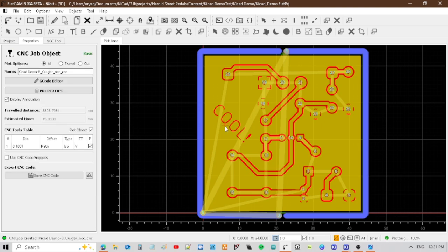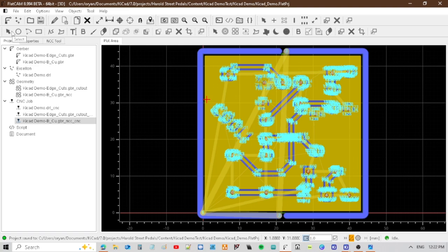Okay, so we did that pretty quickly. Is it going to give it to us? This is where sometimes it'll plot and finish, but the G-code will be empty. You won't get it all blue like it just went. It'll stay red. The numbers won't appear. Save. And that was what that fix was when I made the geometry. I made it a little bit bigger than the bit, and it seems to always work when I do that, and it seems to never have any negative results in my end product. So that's just what I do all the time now to save headaches. I saved, right? We're just going to click it again for good measure.